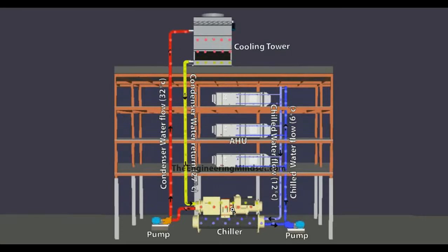Now, chillers come in all shapes and sizes and thermal ratings, and that really depends on how much unwanted heat the building is producing. And this unwanted heat comes from sunlight, people, and the equipment within the building. Even the chiller itself will generate quite a fair bit of heat as it produces this chilled water. So the system will all be designed to cope with this, to reject that heat and produce enough cooling as it was designed to do.